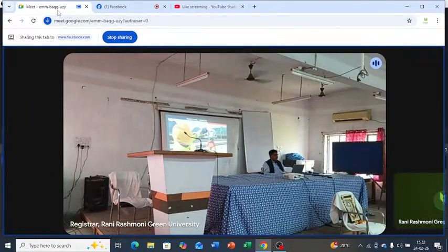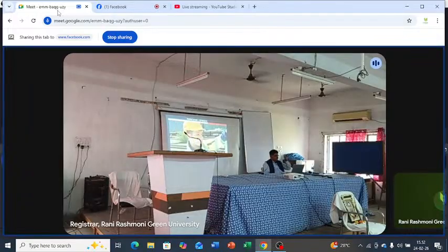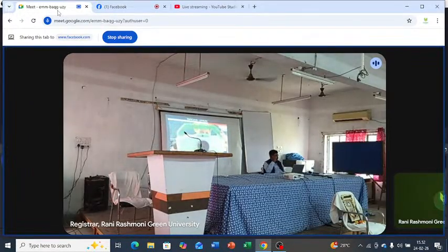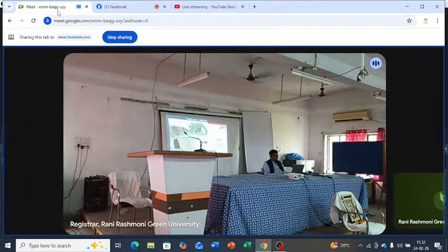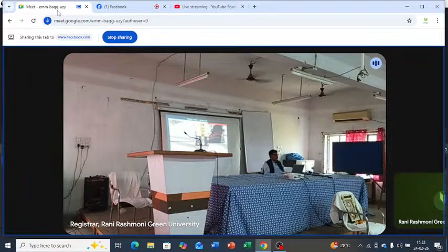It also has a camera, so you can actually see the staff through the camera instead of seeing it through the telescope. Now we can see the staff through the camera. You can have a USB for data transfer. This is the barcoded staff with which it takes a measurement.